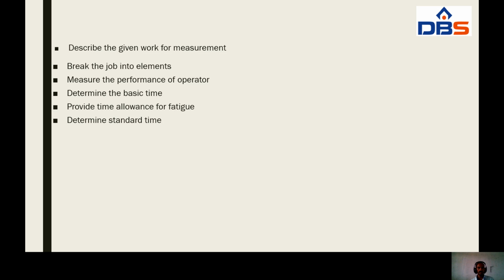And the next, measure the performance of the operator. This means measure the time taken to perform each element. Each element should not take more than 30 seconds using a stopwatch. And the next, determine the basic time.